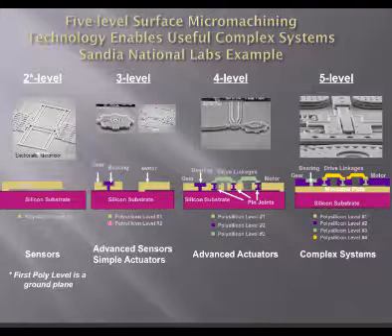So this is a resonator, a very, very simple device. And they designed this so they could test and do calculations. Is my spring constant what I think it is? The way you figure that out is drive it at resonance, find out what the resonant frequency is, and then you can back calculate what K is, the spring constant. How does that compare to the model and the simulations? And then once you learn that, you can build more complex designs, because springs are a big deal.